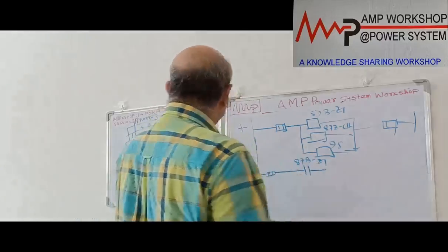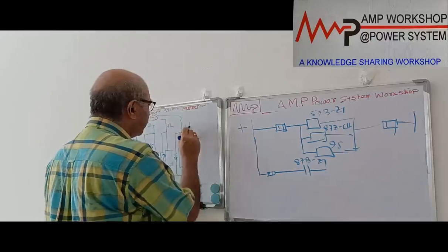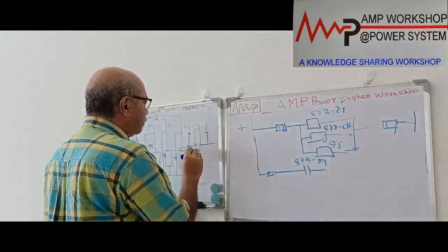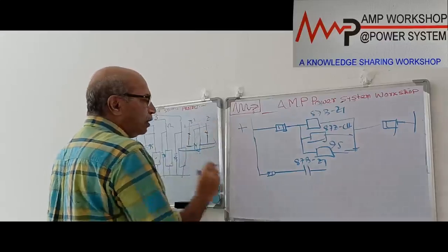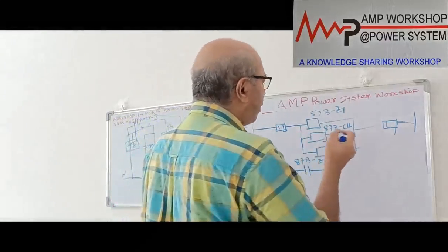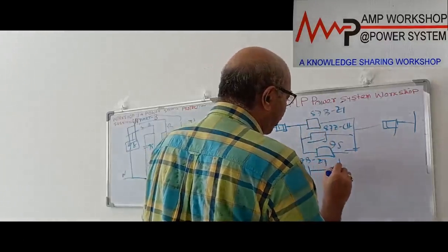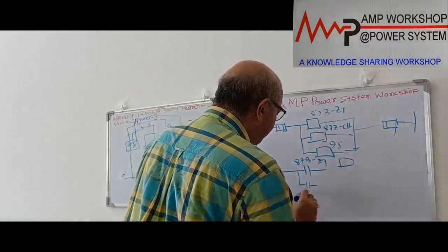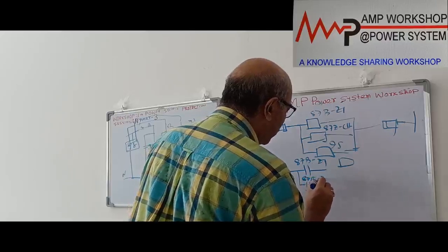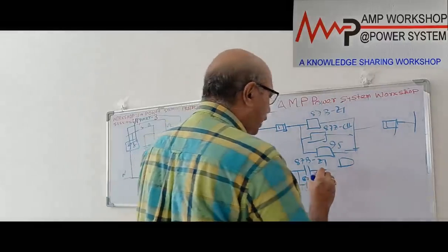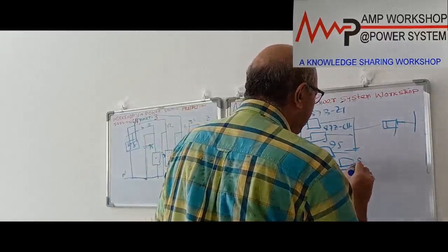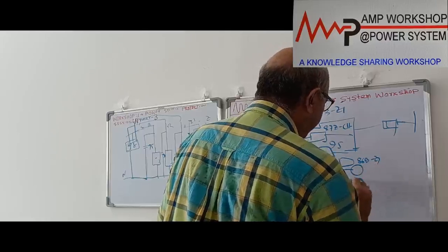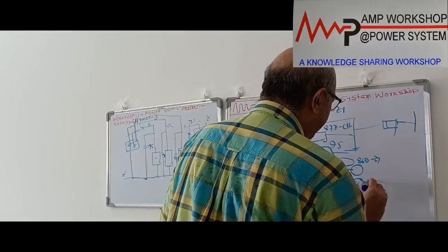So this is zone 1. Similarly, for the other zone, we have shown the bus coupler, so we have zone 2 over here as per our single line. So this is zone 1 and this is zone 2. This is for zone 1. Similarly, zone 2 also will have a similar set of relays connected over here. So this is 87B Z1, and similarly there will be 87B zone 2 relay also, right? These two relays will come to a lockout relay. We have said this is the 86 lockout relay, 86B Z1, and this is 86B Z2. Each zone has a separate lockout relay.